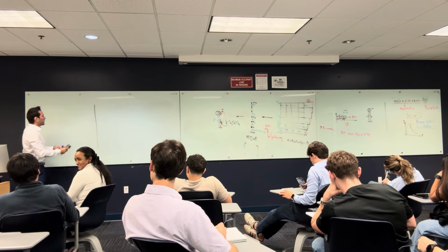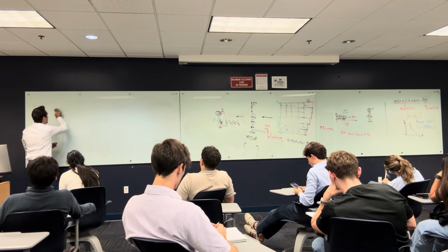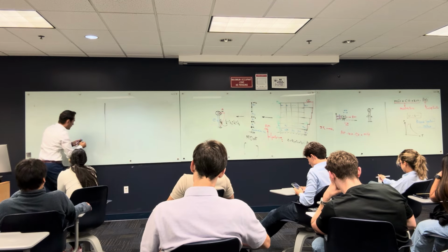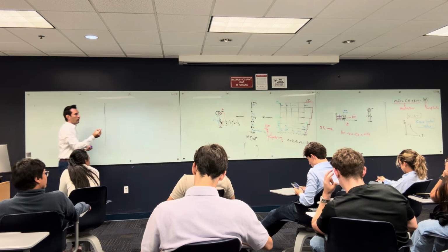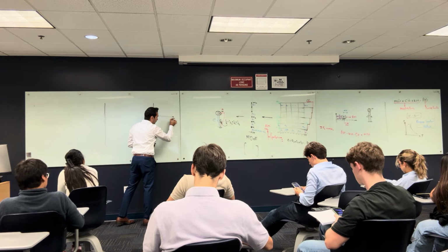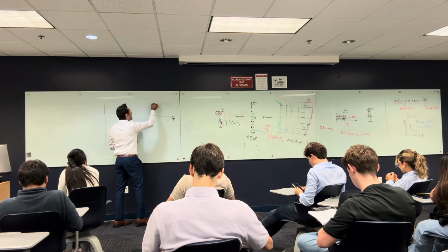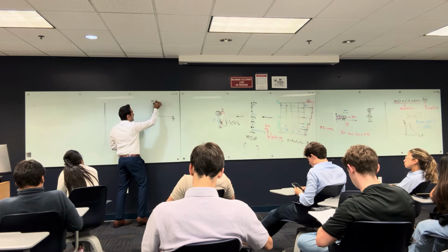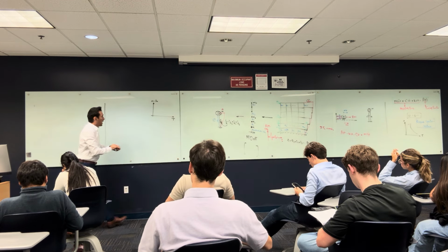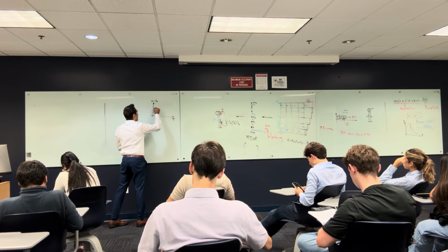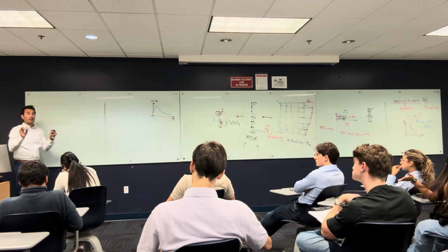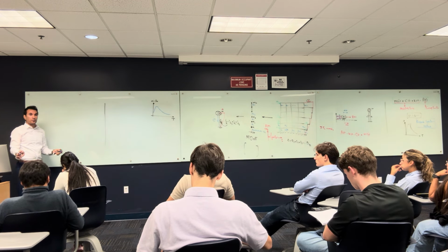Before we talk about the response spectrum method, I want to talk about something very quick. Let's see what is T that I put in this curve. As I said, we need to come up with a curve. This curve is something like this. It has T here, which is called the fundamental period of the structure, and it has the acceleration, which we call SA, the spectral acceleration. We're going to learn what the spectral acceleration is, and then you end up with a curve something like this. This is a very, very famous curve in the structural engineering world. It's called the response spectrum curve.